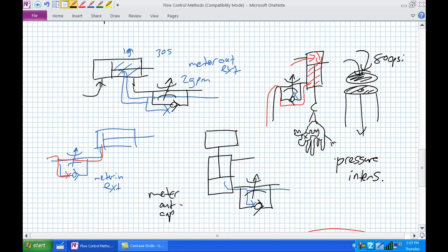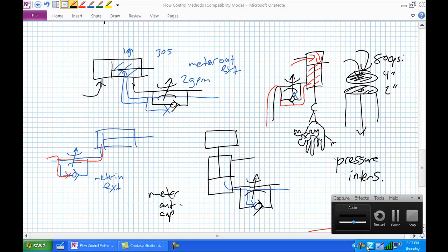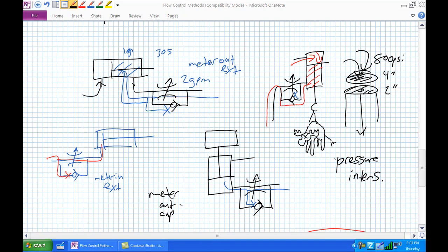Very similar to our series circuits there. Not only do you have, and again, this is a suspended load case here, if it was just the pressure, I mean, this is bad enough. 800 psi, and let's say that is 4 inches on the cap end, and then let's say it was 2 inches on that rod end, that annular area. It's basically going to be double the pressure.